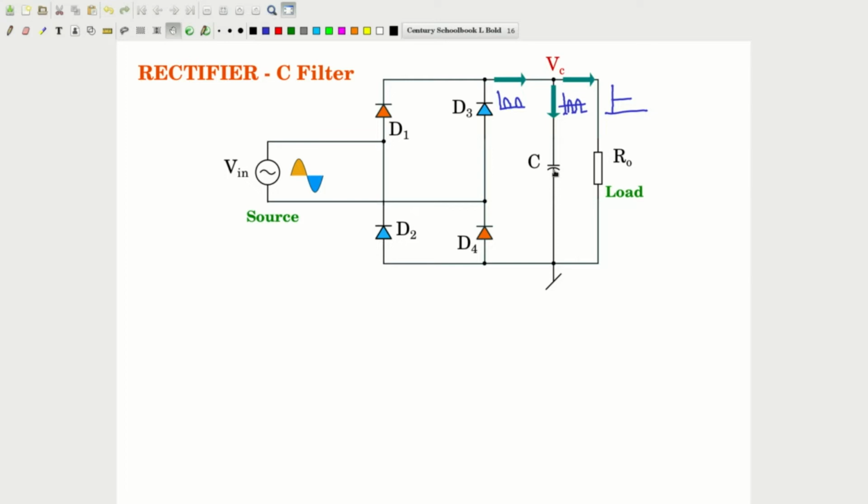You must note that in the steady state, the capacitor can handle only a pure AC current. There should not be an average value, otherwise there will be charge buildup. So under steady state, only the AC component flows through the capacitor. That is the action of the filter.